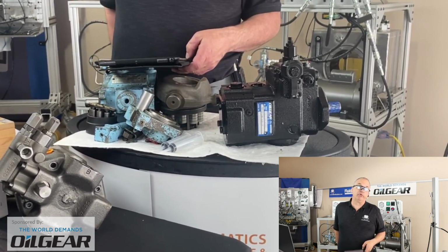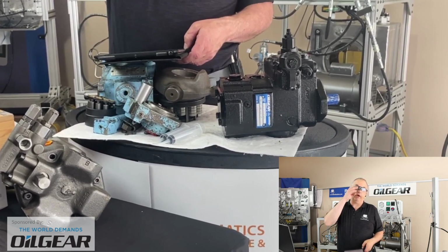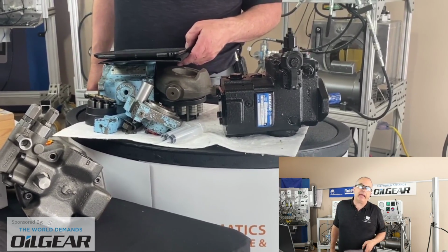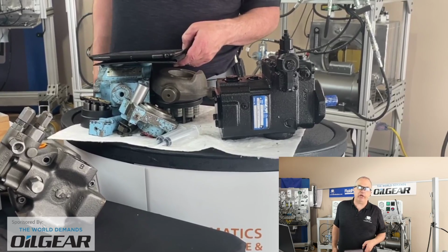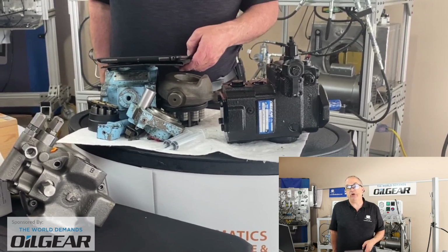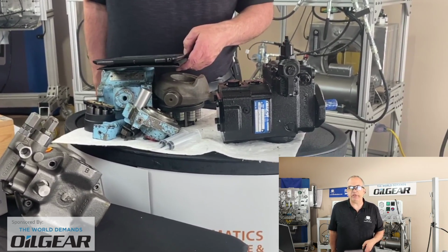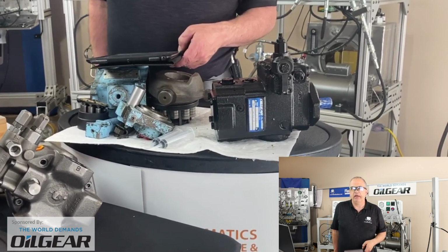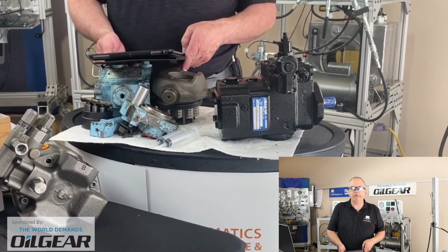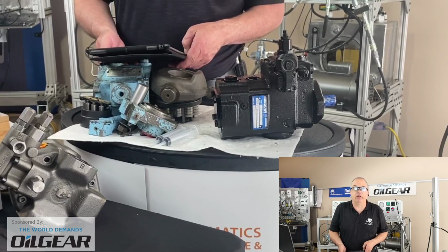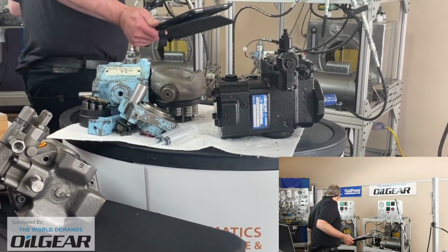So look all over on the pump case. Quite often there will be a directional arrow indicating what direction the shaft is supposed to turn. Sometimes that arrow is just sticking out of the casting in a very nondescript way, and it's got the same color paint as everything else and can be a little hard to see.